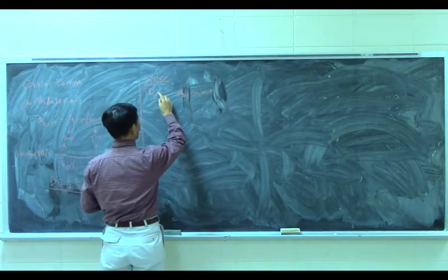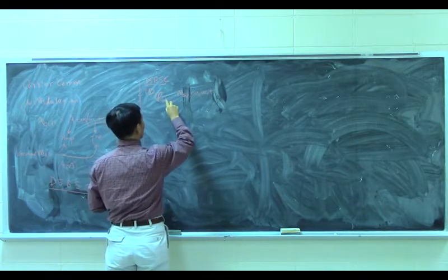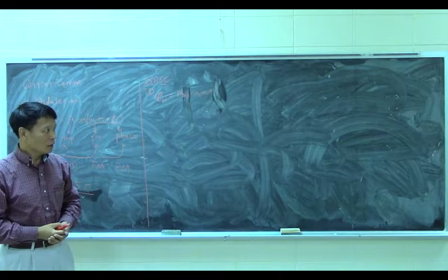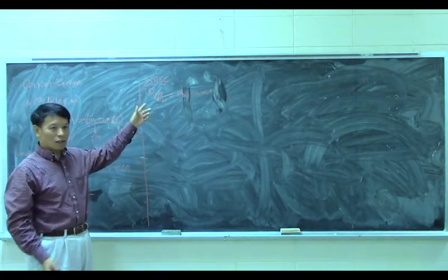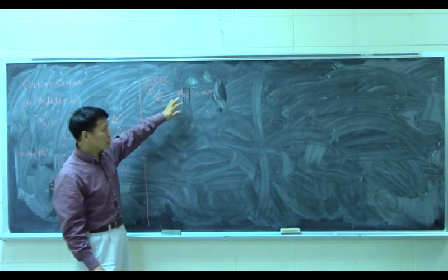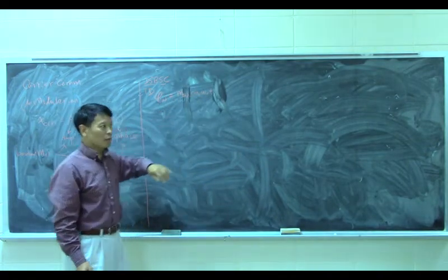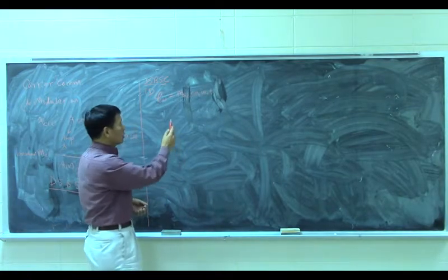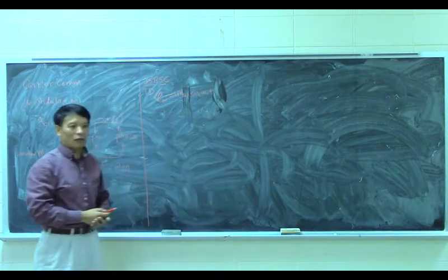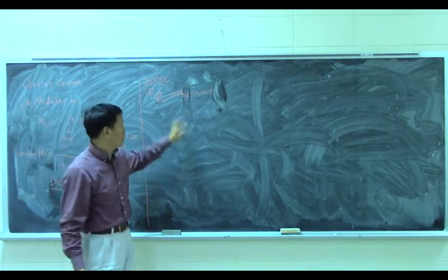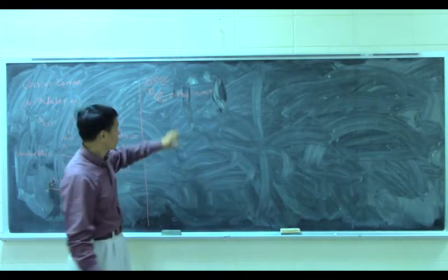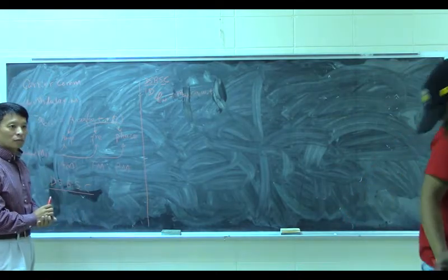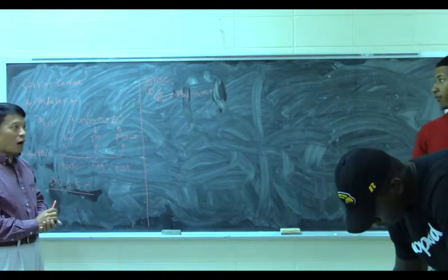This one is the modulated signal. So we are going to represent this time domain signal with phi as a function of t. So phi(t) equals m(t) times cosine omega_c t. So in time, you can see this modulation is very simple, right? The baseband information multiplied by the carrier signal. Sometimes you can see there's an A constant here multiplied by A, so that's fine. We can assume A is unit 1, so that's not a big deal. The key here is the baseband information multiplied by the carrier signal. So that is the time domain representation.